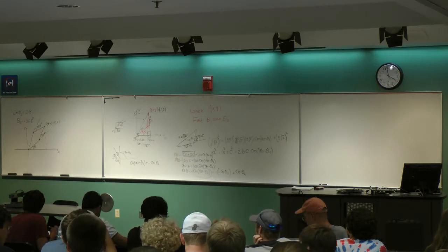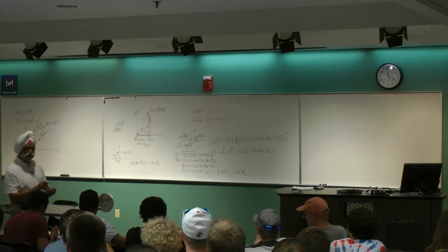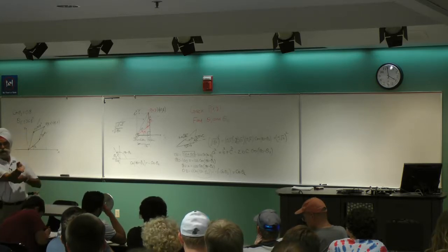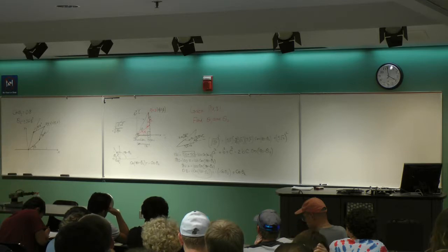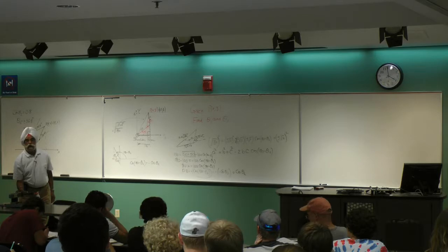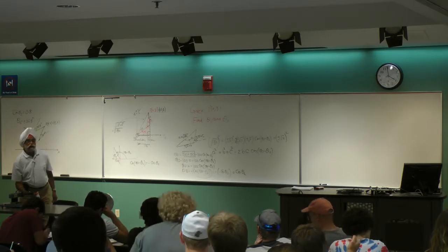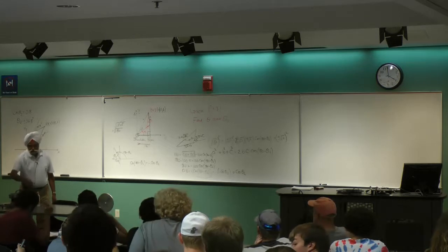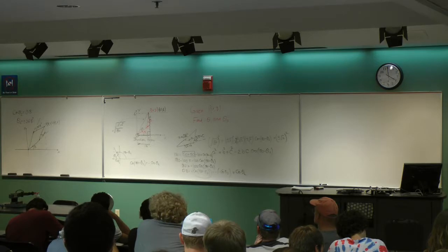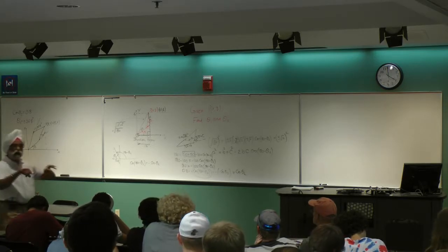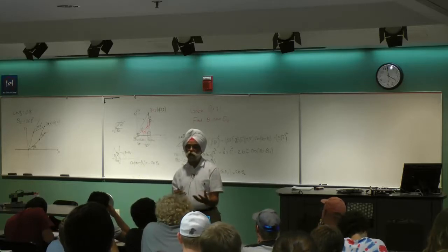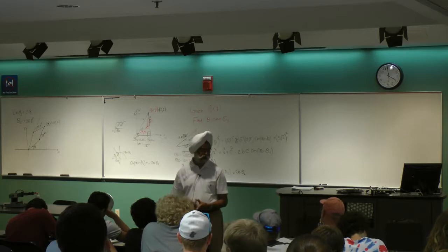Same angle, but negative. Now it's elbow down. When you have a positive angle, we call it elbow up, and the other way is elbow down. This is elbow down because you are going in the clockwise direction. When you go clockwise, you have elbow down. This elbow is down; the other way, the elbow was up. So you basically have two solutions, multiple solutions. But compared to theta 1 equal to 36.8, you have a different value of theta 1 for the other one. And we're going to find that.